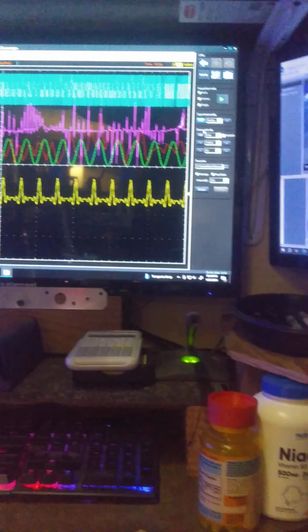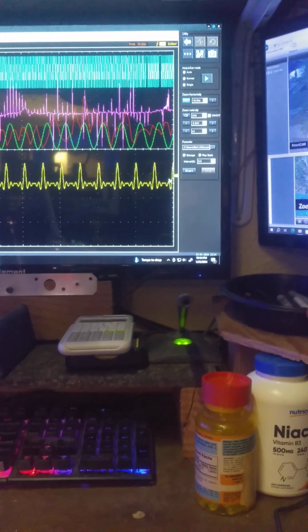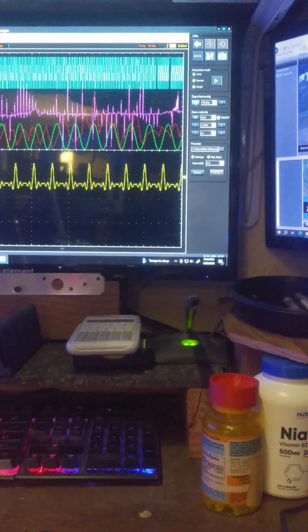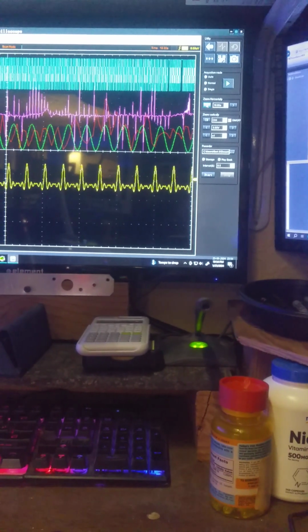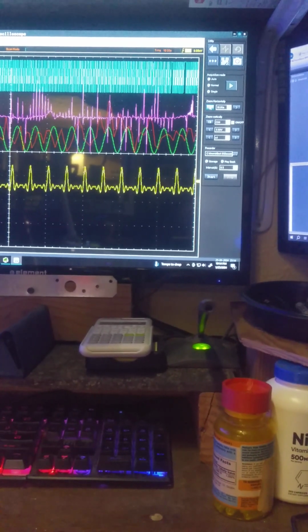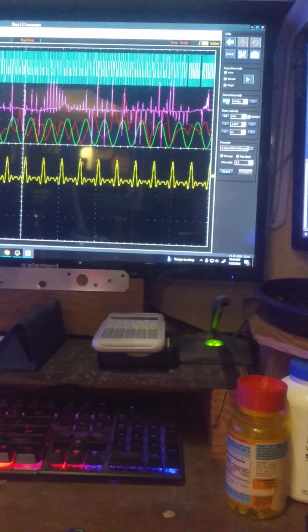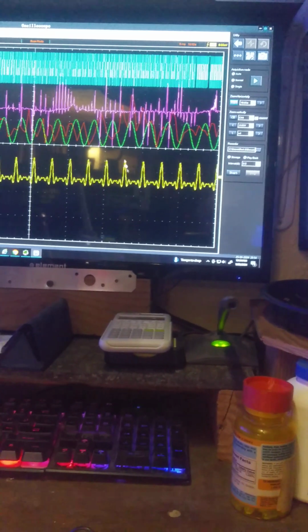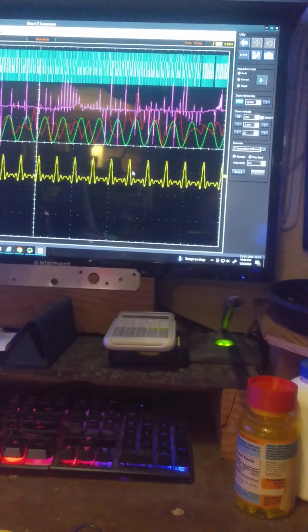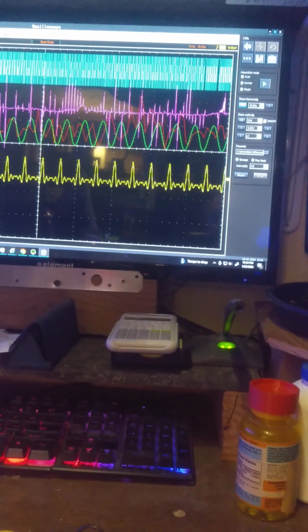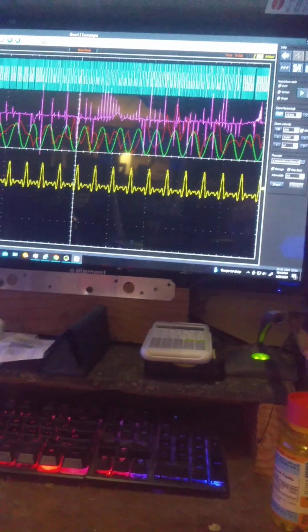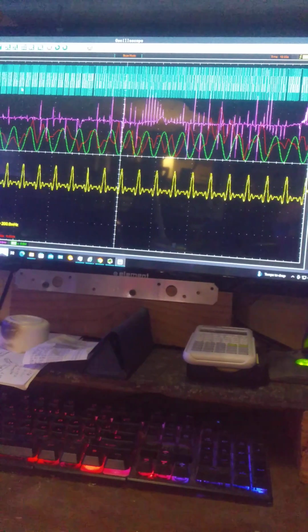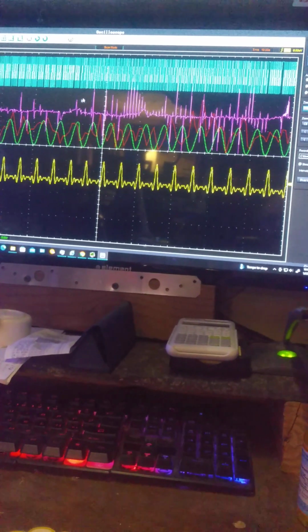But anyway, the point is that you got aliasing effects here that can show you on some of these cheap scopes a signal that really isn't there. I mean, it's the same exact waveform. Just like this is actually not the same waveform, because it should be synchronized with a square wave, but these are too high frequency for it.